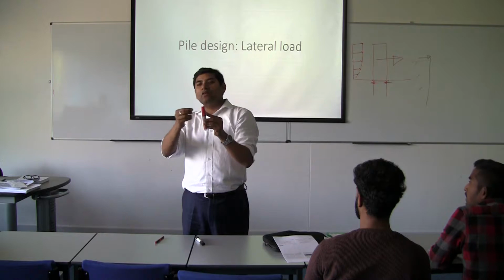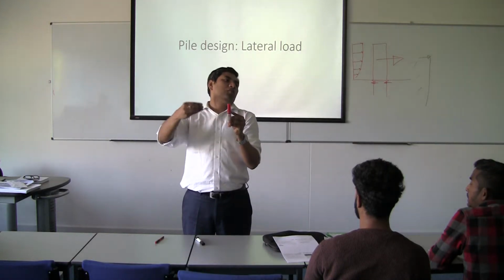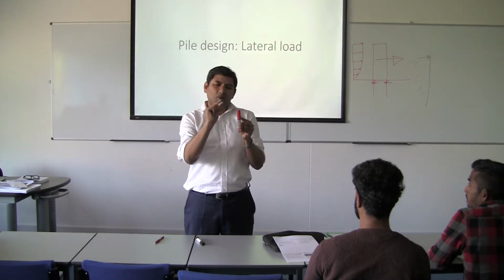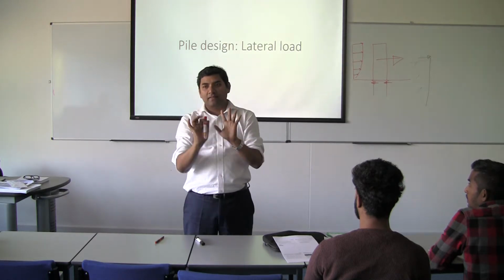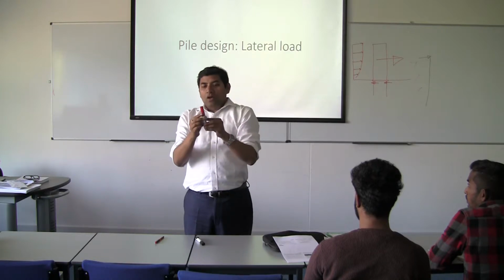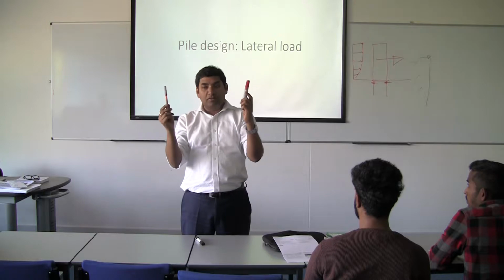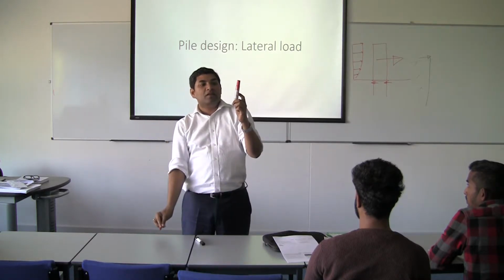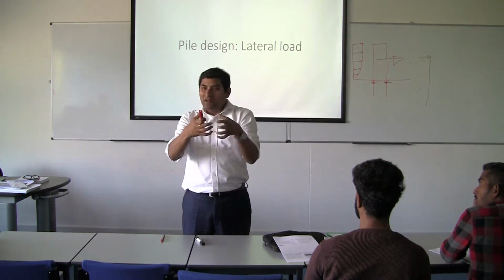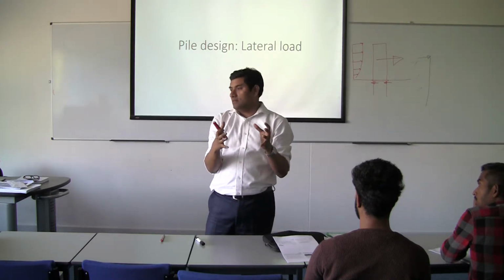So if you apply a load, you get displacement. More load, more displacement. More load, more displacement. Proportional. But you will see a certain point where a small change in load gives big movement. That's a failure. Do you agree? Yeah? So if you assume that definition, both of these piles will fail. In this case, when it fails, the soil would fail, the pile will not fail. The pile would be sort of undamaged.